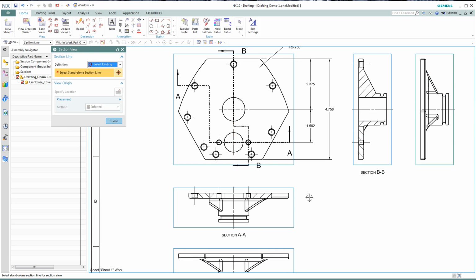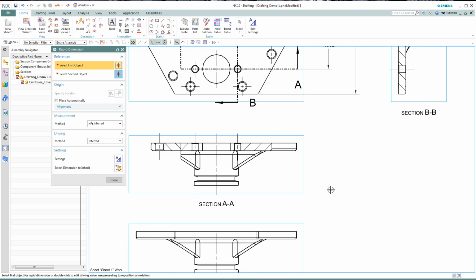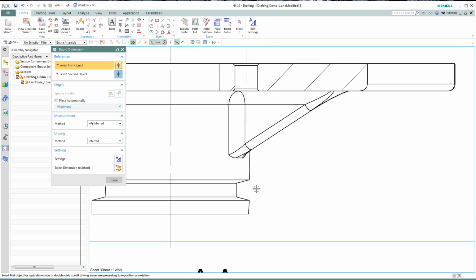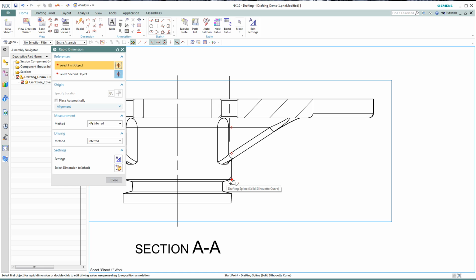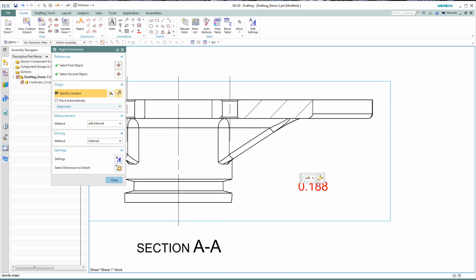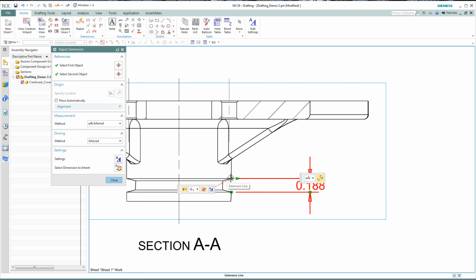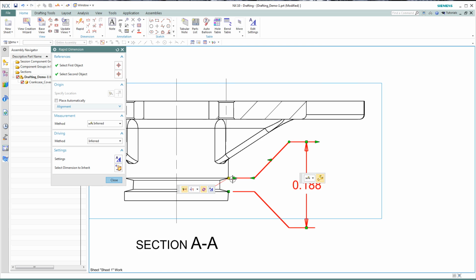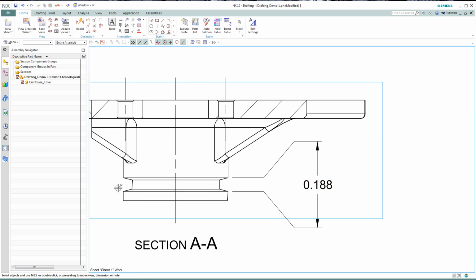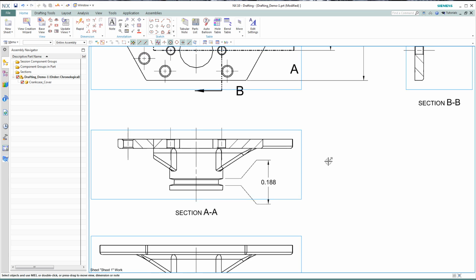Now that is done, we want to go ahead and add more dimensions to show some of the new functionality, that we'll now be able to create a jog. When we have a dimension that is tied close, we want to be able to create a jog. In this case, we want to go ahead and edit that dimension. Make sure everything is synchronized on both sides. We want to create a jog. So now we can just go ahead and define that, drag some of those hot spots, undo our edit, and you'll notice that we have a jog on our dimension.